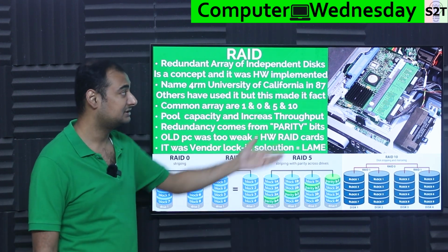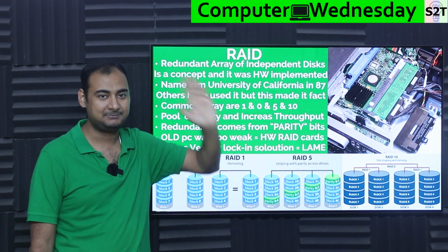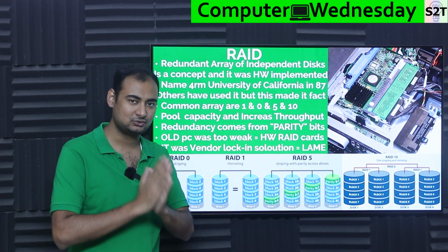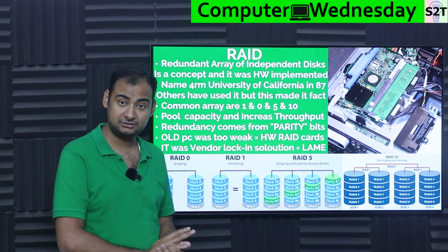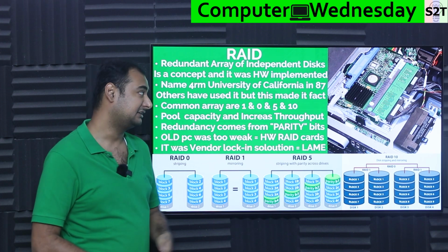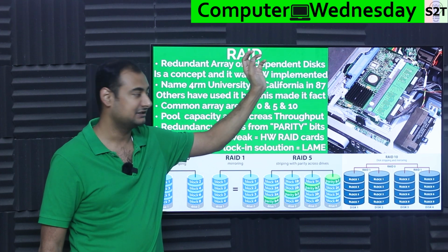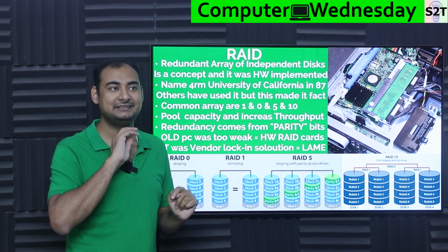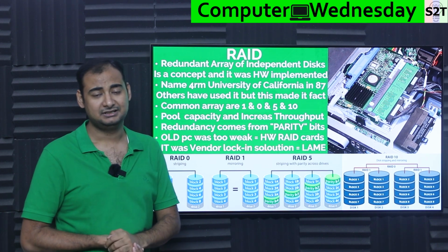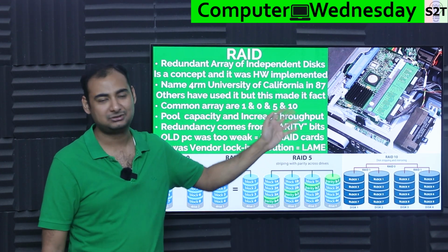So what was the solution? The solution was a PCI Express card, and they put a whole computer in that. Basically, they put ASICs, application specific integrated circuits. The whole system was designed as a miniature computer whose sole job was, I do parity calculation. And they were very good. It did work. And again, you can see they had RAM, they had batteries. Why? Well, it's a computer, and the problem was that if data was dumped into the RAM and power went out, there was nowhere for the data to go. Be mindful, this is the 90s, so there was no flash storage. The idea was very simple: have a battery, and it should last at least 24 hours.